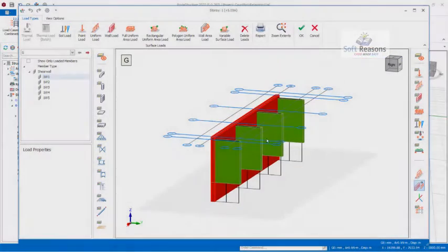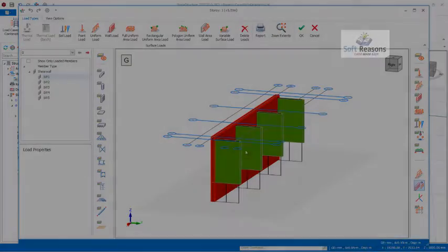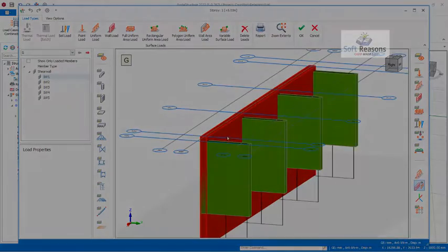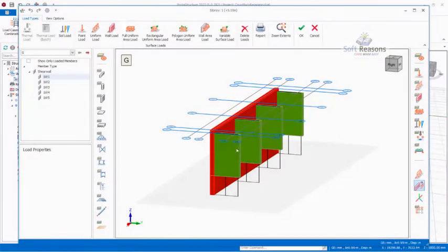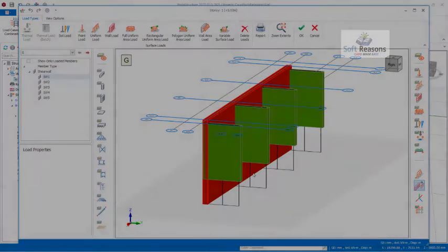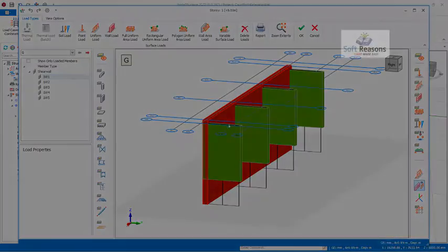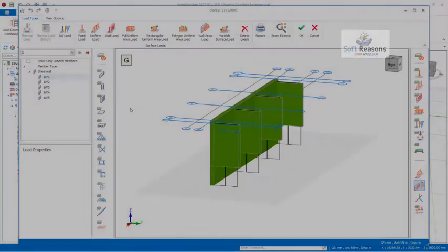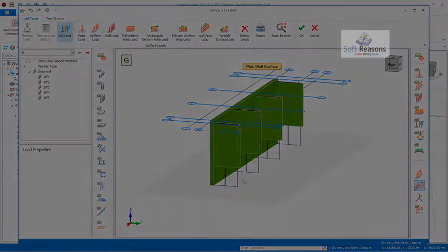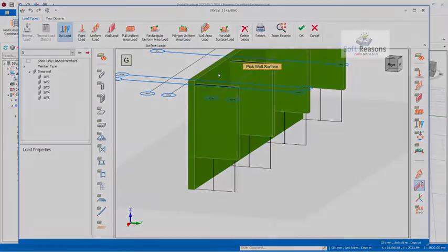All of these other 4 walls are support walls, to be able to actually hold the main wall in place successfully. This type of wall is actually recommended in a situation where we need more passive pressure to withstand a very high active earth pressure successfully. So we click on the soil load, after which we select the face of the wall to apply the load.